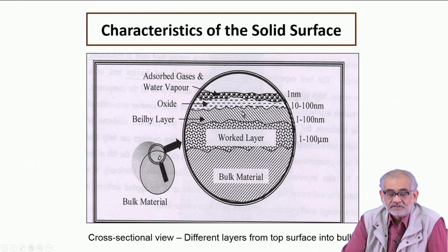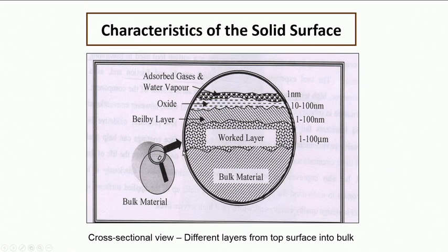And then we have, of course, a certain amount of deformed layer where we have a density of various kinds of defects, but essentially below we have the solid that we generally tend to deal with. So in other words, when we talk of a big bulk solid, we tend to believe that this bulk is exactly the same throughout. We just saw that the top of the solid-vapor interface is structurally different and certainly carries a certain amount of energy.